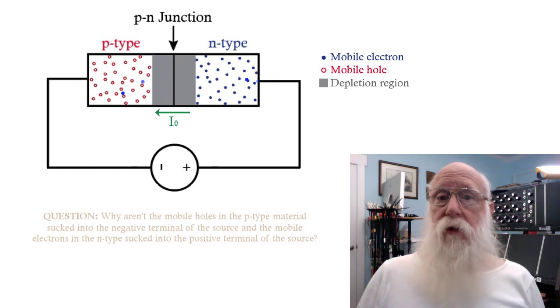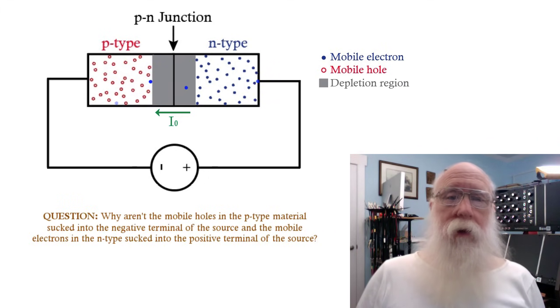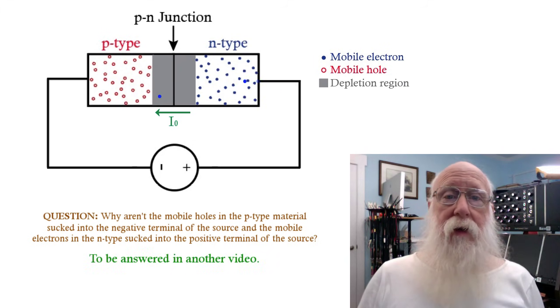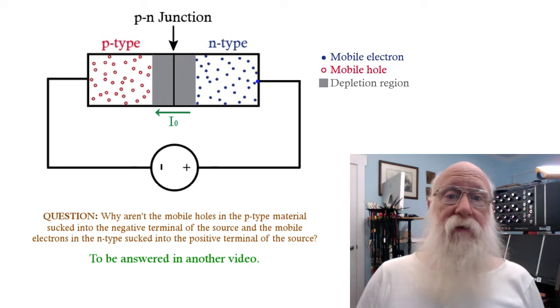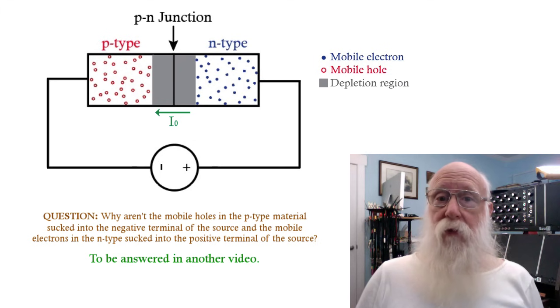This current is usually incredibly small, but it does depend a lot on the device, and it might be in the picoamp range or the nanoamp range, but in general they will be very small. Since this current is primarily due to heat energy freeing up mobile charge carriers, this reverse saturation current is very dependent on temperature.